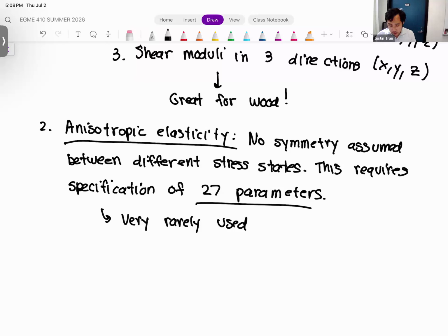Okay. Another aspect to consider, and this is a factor for both orthotropic and anisotropic elasticity, is the limitations and how ANSYS will allow you to specify this. This isn't in the notes, it's just a difficulty that I've noticed observationally over the years. When you apply any kind of directionality in your material properties within ANSYS, you're limited to the Cartesian directions.